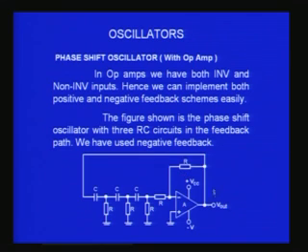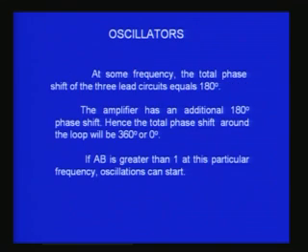So this is the circuit corresponding to an RC phase shift oscillator using an op amp. You did not find much difference from the transistor amplifier, except that I have removed the common emitter transistor amplifier, and in place of that I have introduced an inverting amplifier using an op amp, which we have all seen earlier. So now at some definite frequency f, 2 pi f will be omega, and that will introduce at that frequency exactly 180 degree phase difference with the combination of 3 RC networks.